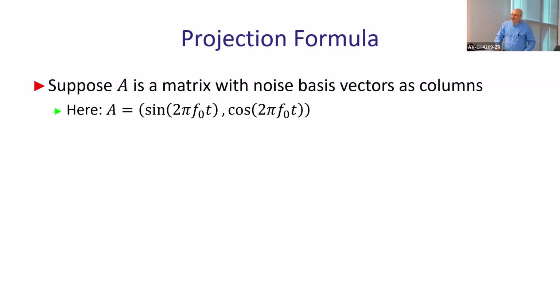Any other questions? Yes. So if the signal is not periodic, then we cannot use Fourier series to represent it. No, you can't. For non-periodic signals, you need to use the Fourier transform. Then it will work. Fourier series is only for periodic signals. It needs to repeat every period.